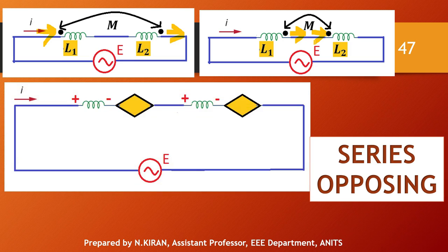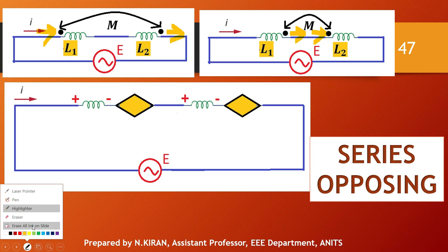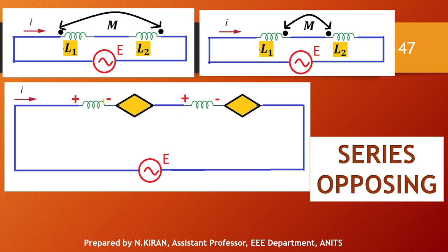Trying to find the electrical equivalent of this circuit, the polarities for self-induced EMF will remain the same, that is positive, negative, positive, negative. Since current is entering at the dotted terminal of the first coil, we look at wherever the dot is located in the second coil, in this case it is the extreme right.